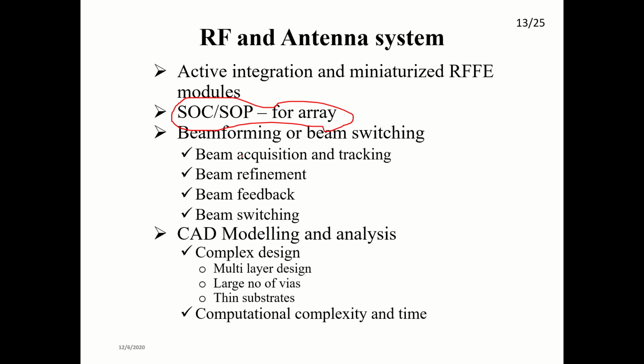In the system on chip concept, one layer will have antennas, another layer will have the baseband processing unit, and in another layer we may have some other components for the transmitter chain or receiver chain. For beamforming networks also you may have layers, and through vias, all are interconnected. So that's where system on chip, system on package, or PCB is coming up in